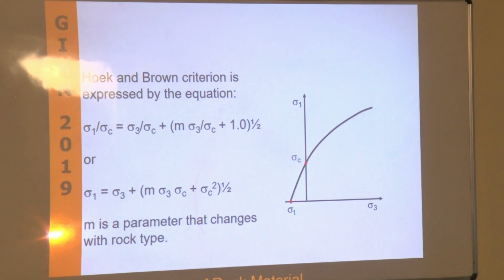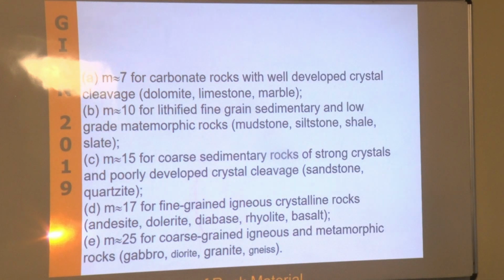By relating the large-scale response of the material to a rock classification that we will see tomorrow, it became a very useful and widespread strength criterion specifically for rock mass, because it has a classification and also a number that can be directly used in numerical models. And that was really the big contribution that they made.